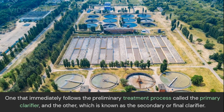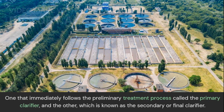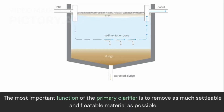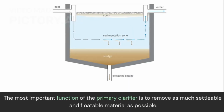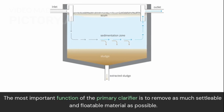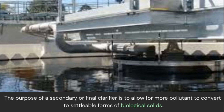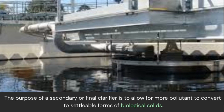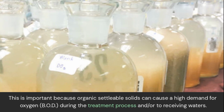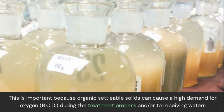One that immediately follows the preliminary treatment process is called the primary clarifier, and the other is known as the secondary or final clarifier. The most important function of the primary clarifier is to remove as much settleable and floatable material as possible. The purpose of a secondary or final clarifier is to allow for more pollutant to convert to settleable forms of biological solids. This is important because organic settleable solids can cause a high demand for oxygen, BOD, during the treatment process and/or to receiving waters.